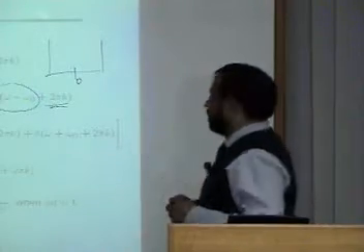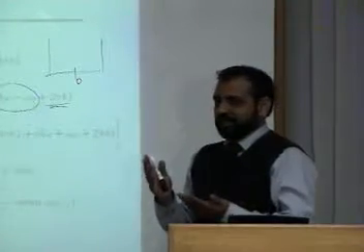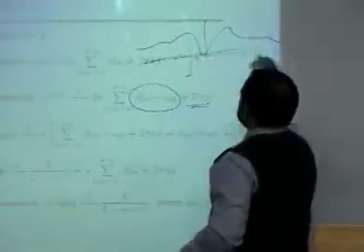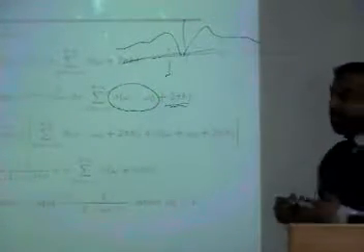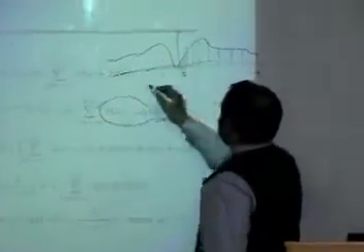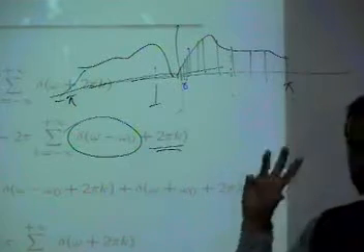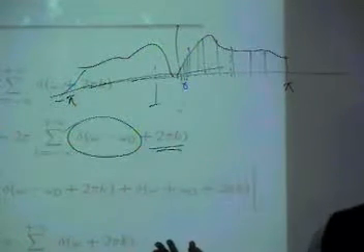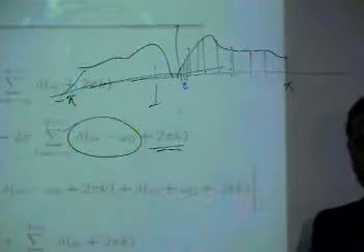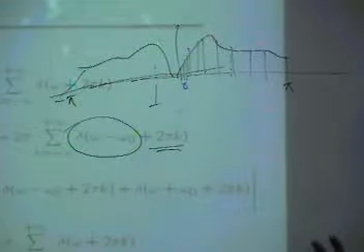What we really infer from this is that once you look at the Fourier transform of any x of n, it will have not impulses but a spectrum, something like this. It means that this signal has all these complex exponentials, from 0 to pi and minus pi. And this is important: any signal can be broken into infinitely many complex exponentials of different magnitude. Fourier basically concluded this, that any signal, whether periodic or aperiodic, can be broken into infinitely many exponentials.